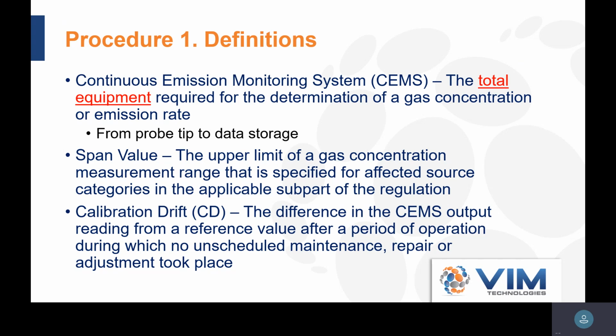So you have the sampling system bringing the exhaust, filtering it, removing water from it, sending a clean, dry sample over to your analyzers, and then your analyzers give you a concentration reading, and that reading is used to determine your compliance, whether it's a ppm based limit or a mass emissions based limit, or whatever the case may be.